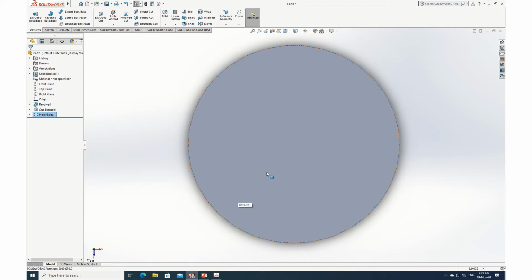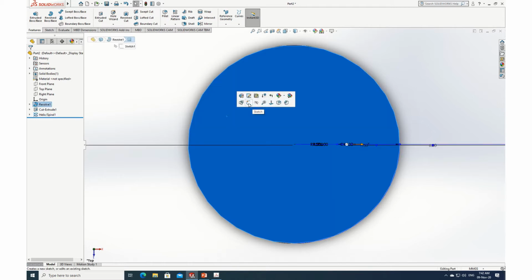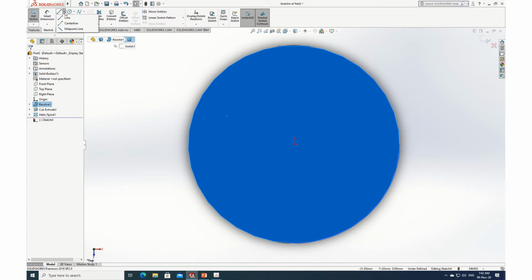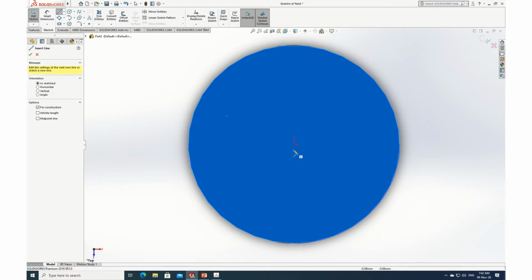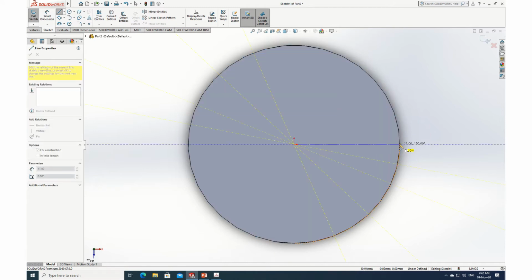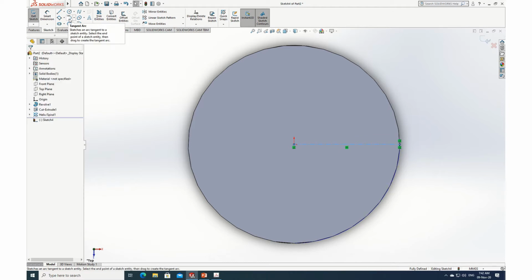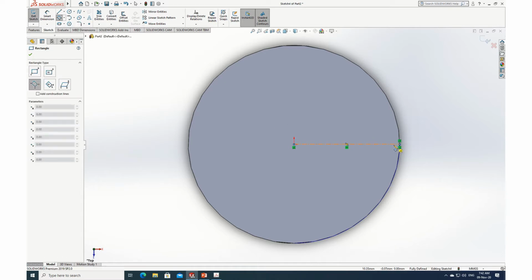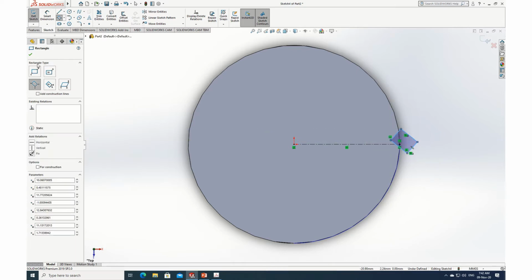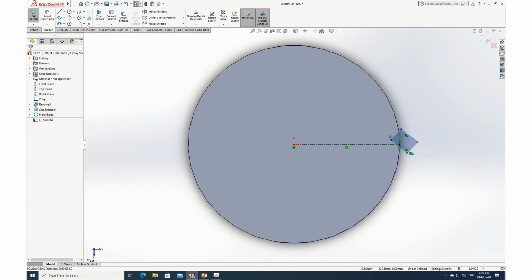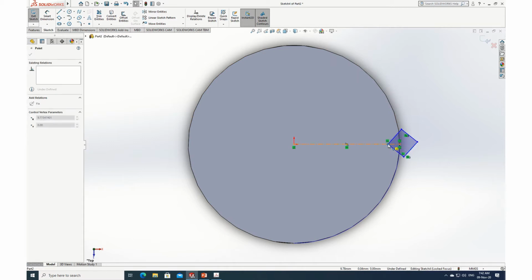Now what I will do now, I will just go select this face, I will make edit, I will just go draw one center line. From here I will just draw a center line to this point, enter. Okay, I am not drawing a solid line because it will be used later in all our operations. So now I will just go take this 3-point rectangle, first point somewhere, I will do it here, just draw a rectangle, that's it. Okay, so it is knurling. So I am showing you how to do typical knurling. Okay, let me just hold this one, pull it down to be on this line somewhere here.